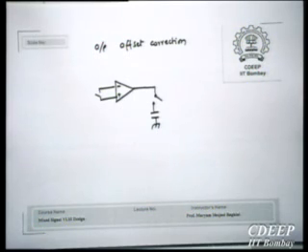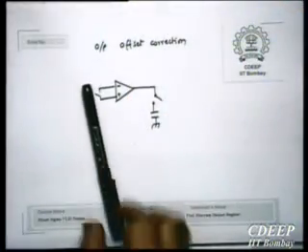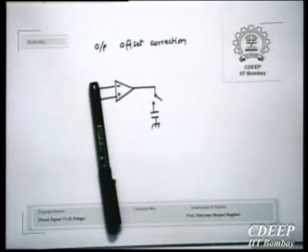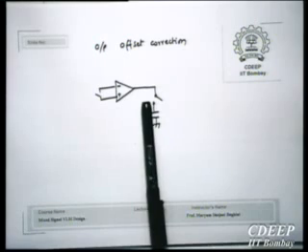This is a non-ideal op amp and it might be the input stage of an op amp, and maybe it has some feedback etc. which I am not fiddling with. So overall gain in this configuration is finite. So as a result, when I give it 0 input, its output is non-zero. And how much is the output? Offset times the gain. When we define the offset at the input, offset times the gain appears at the output. So this capacitor then gets charged to the output offset voltage.